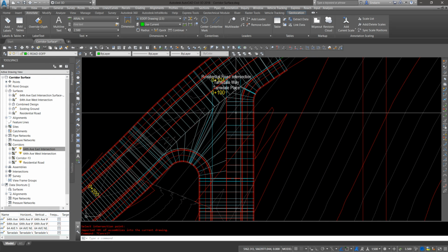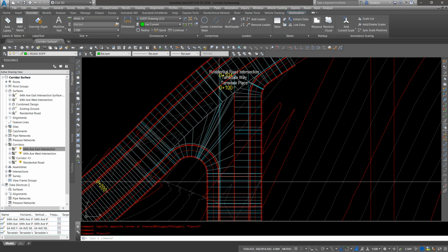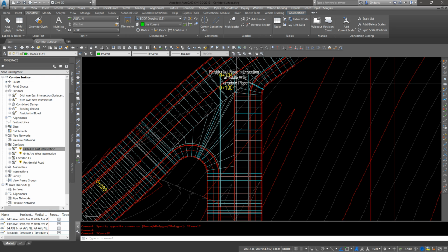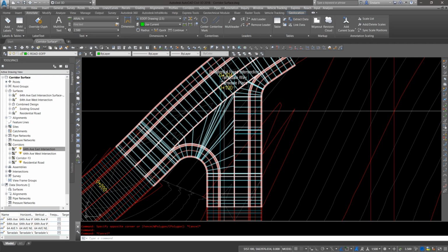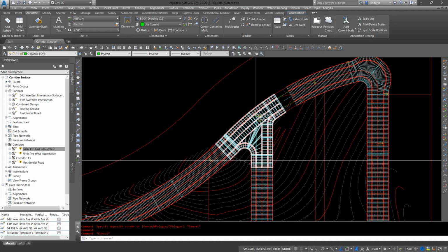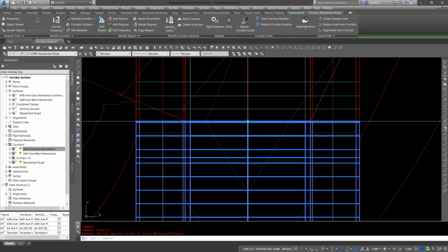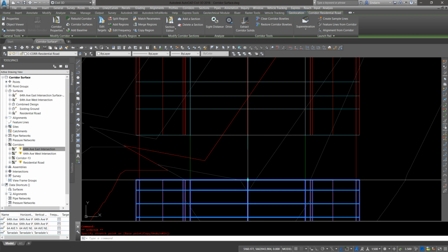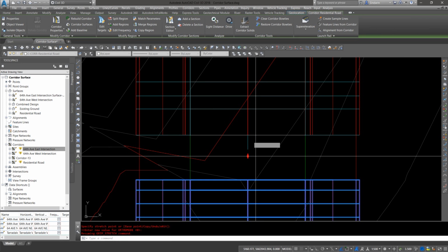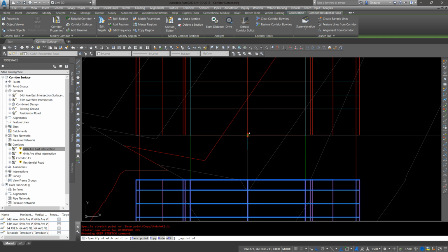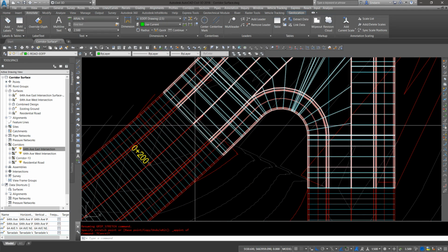And I've actually already fixed the corridor where it was going to create issues. But what it was building, it would build your road lane up into here, up here and across. So your road lane was cutting into the other direction of travel. And it was just causing some overlap issues and bumps in the road when you go to create a surface. So I'm just going to cut these back now. Tie it into here. Tie all 3 roads together again.